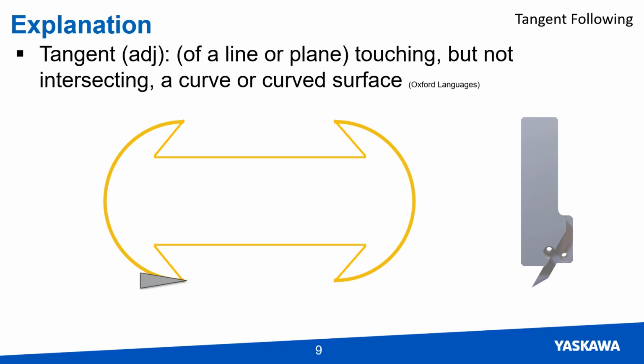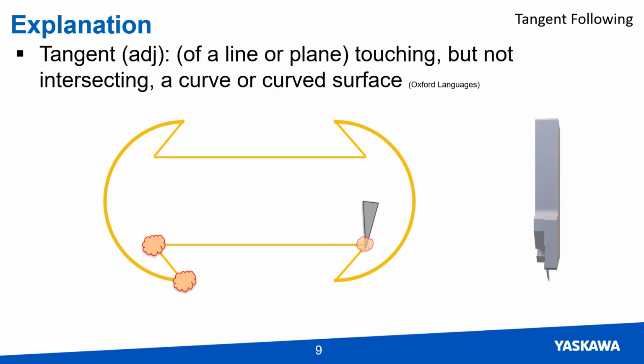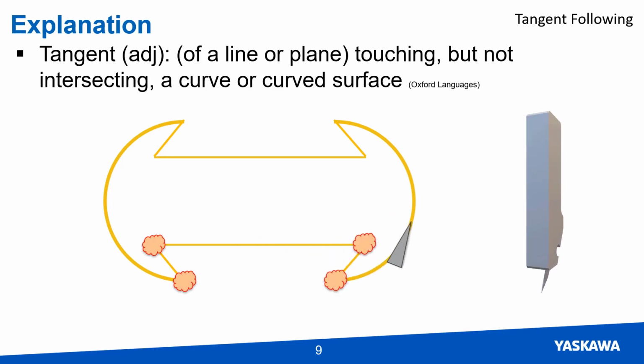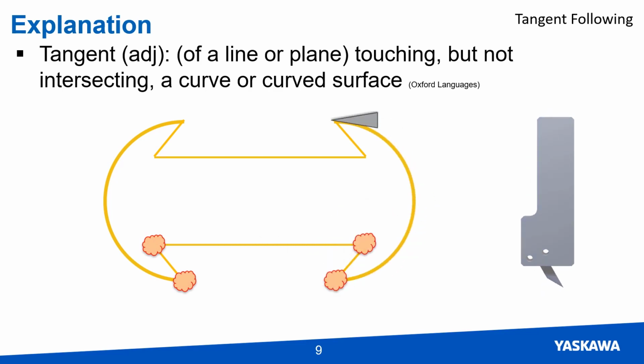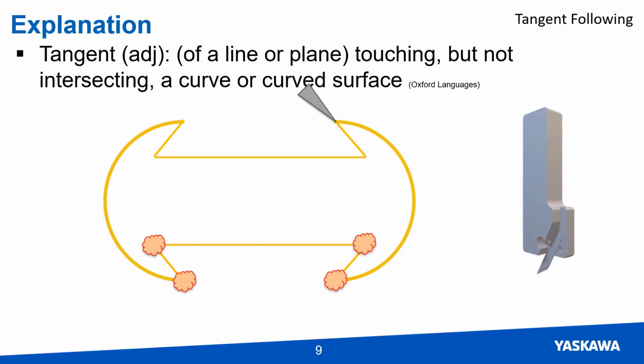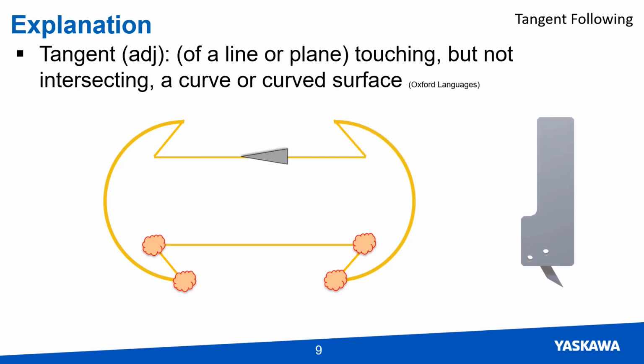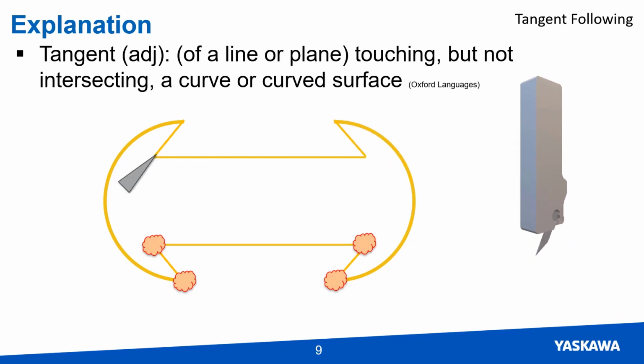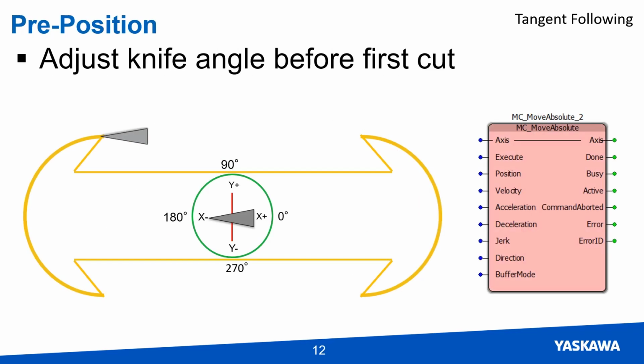If a direction independent tool was used, the tool head would just continue cutting along the path. With the direction dependent tool, if the blade was rotated in the material, it could rip or tear the material or break the knife blade. The blade needs to be lifted out of the material, rotated, then plunged into the material to make the next cut. This allows the material to stay intact and the blade will be less likely to break off. The programmer needs to specify the rotation required for the knife to line up for the next cut.